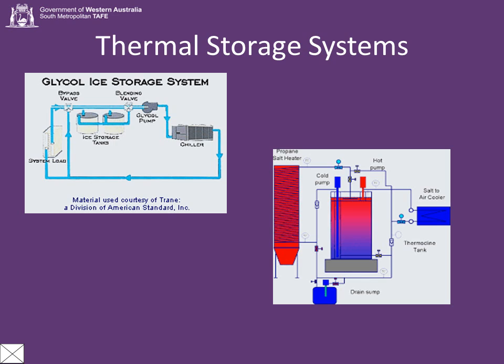We use salt because salt has a higher thermal capacity. So we use it to make very, very cold ice, and we store that ice. Then during the day, rather than running the chillers to cool the water, we just run the water through the ice, and that cools it. We can also do this for heating. We can actually make very, very hot salt, and use that for storing heat.